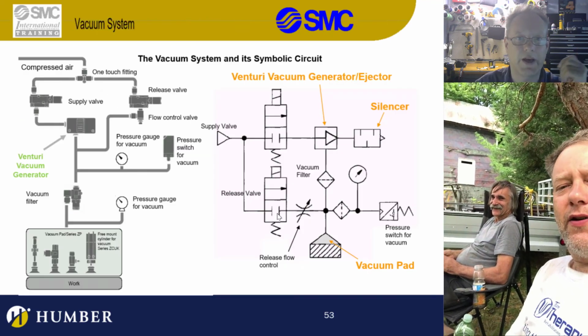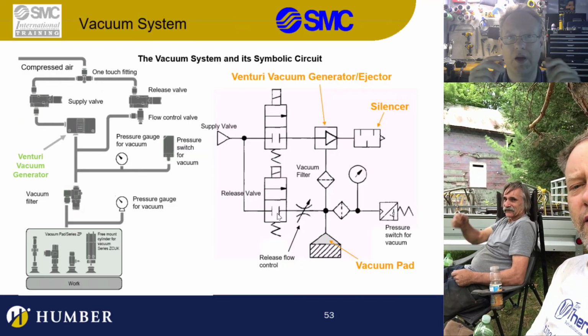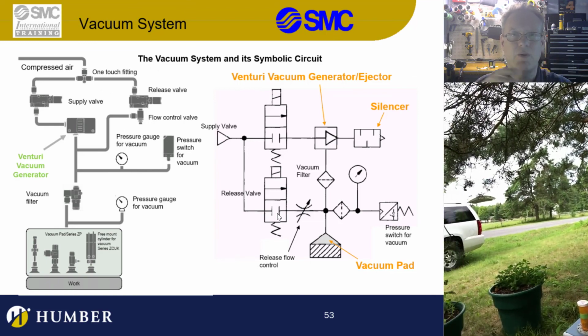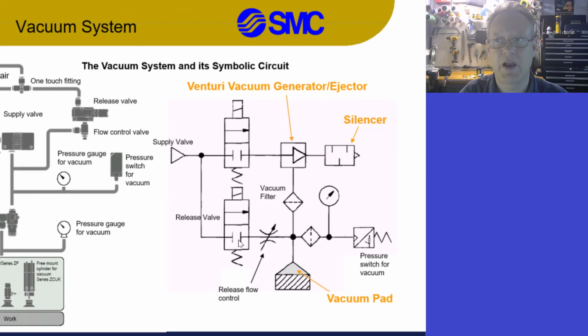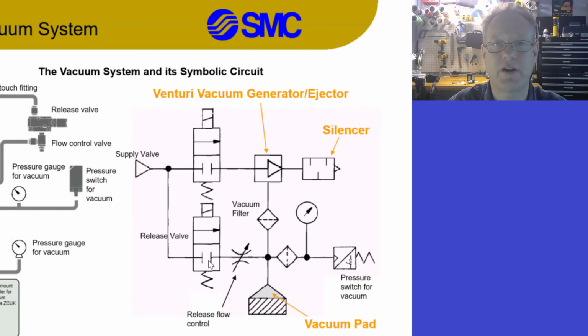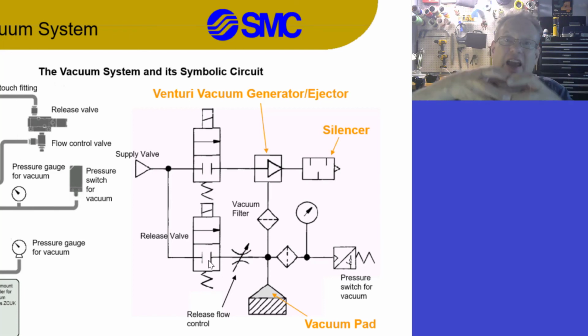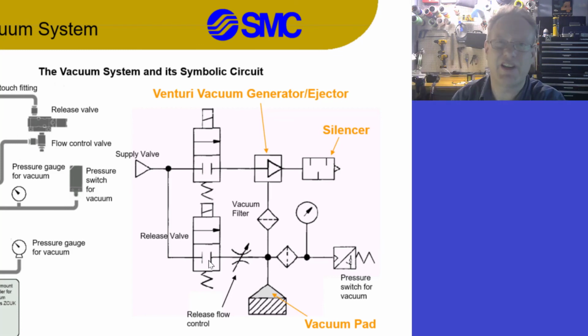It's pretty simple, okay? So now, I need to let you guys know about one thing before I let you go. Essentially, when we're designing the valves and stuff to actuate these things, I need to design a valve that actually blows a burst of air. Wait a second, really? Yeah, because there's that vacuum sucking it up, but then I have to release it. I don't want to just stop sucking, because if it's a really good seal, it's still going to hold. So I want to stop sucking and blow air, and then it falls.